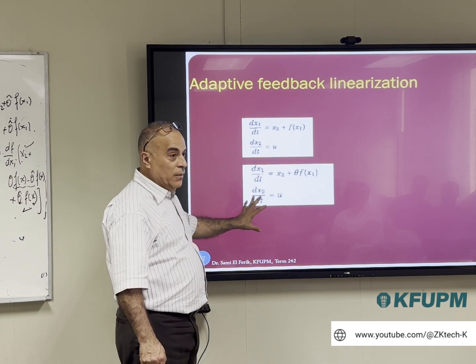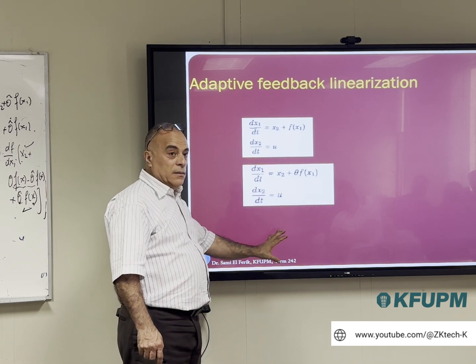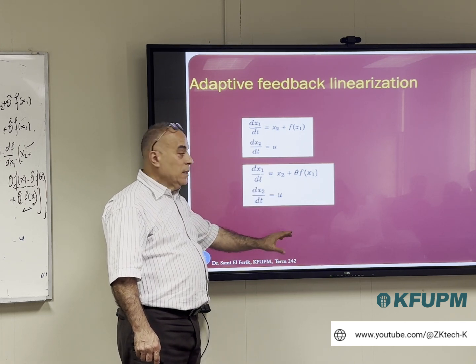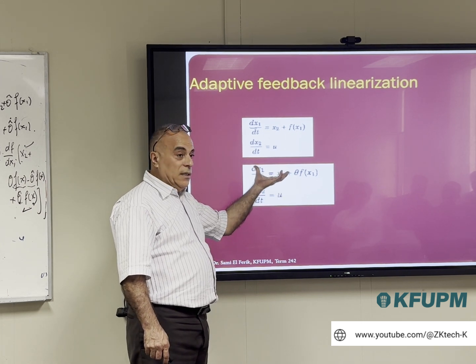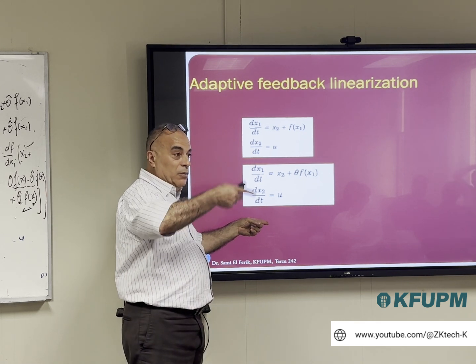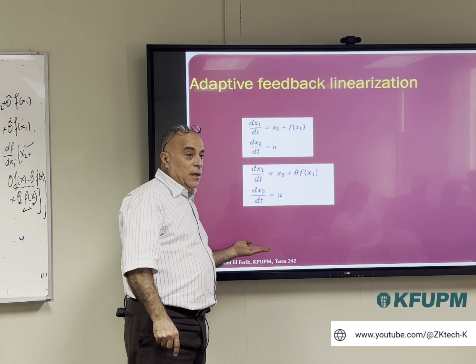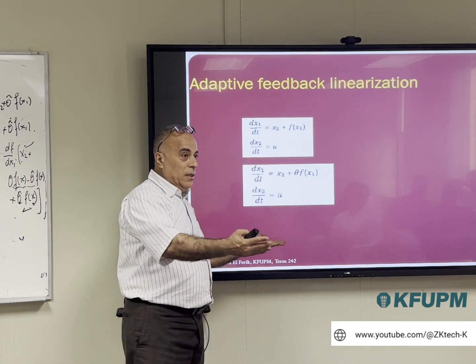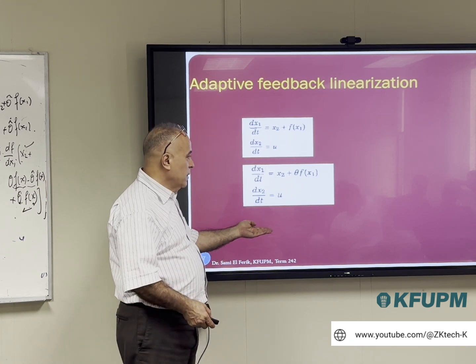Either we transform the state space into another state space that has the nonlinearity at the level of the input, and everything else is linear. Or we go to the output and we keep deriving the output until we have an input-output relationship between u and the output where the nonlinearity appears. And then we try to make the cancellation.